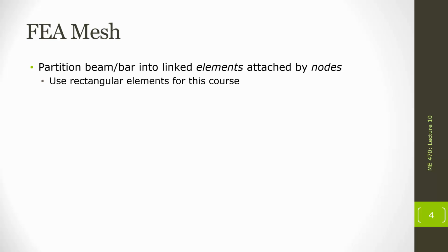And the type of problem might tell us what shape is best to break our problem into. Especially as we get into two-dimensional systems, maybe a rectangle is not the best, a triangle might be better, or some other shape. But it might be dependent on the type of problem we're looking at. Is it a modal analysis like we're doing here? Is it a static problem? Is it a dynamic problem? Is it going to be a thermal problem, an electrical problem? All those types of things are going to have some shapes and some methods that work a little bit better than others.